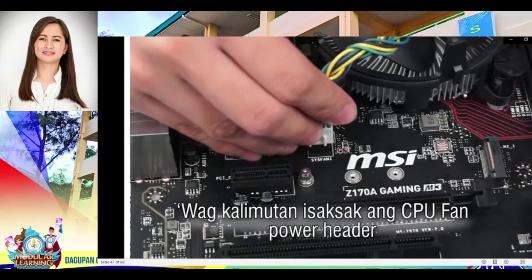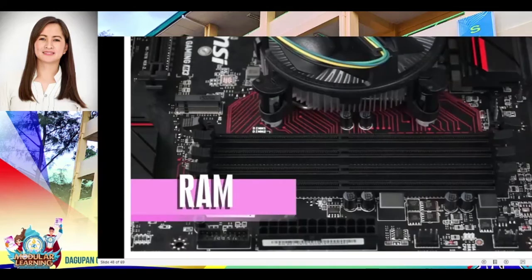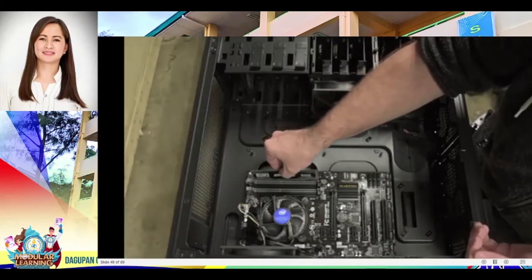The CPU fan is really a combination of a heatsink and a fan together. The unit draws heat away from the CPU. To install the fan, apply the thermal compound to the CPU following the instructions provided with the compound. Pull the locking rod down on the fan assembly to lock it into place.